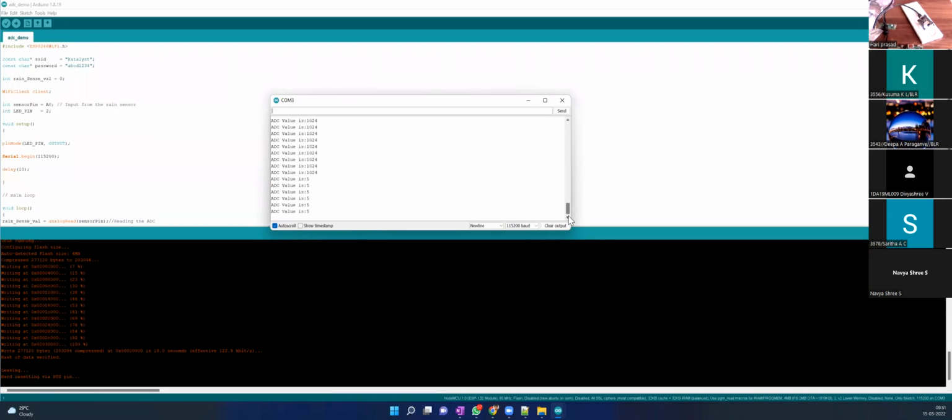This ESP is connected via my laptop, right? My laptop grounding might not be correct, because it depends on home grounding. My house grounding might not be exactly 0 volts. So that's where we are getting some 5. It's almost 0, right? It's the lowest value. So now let me make one small setup.